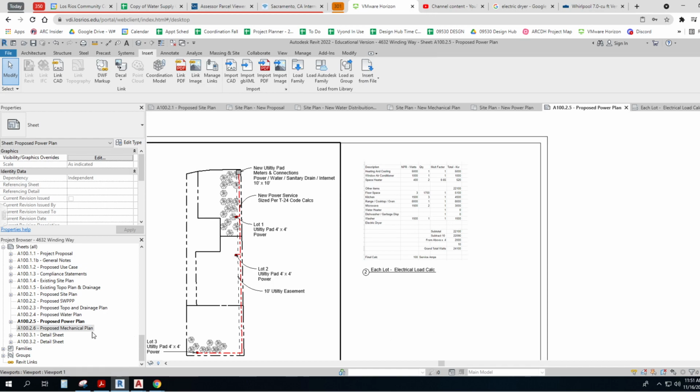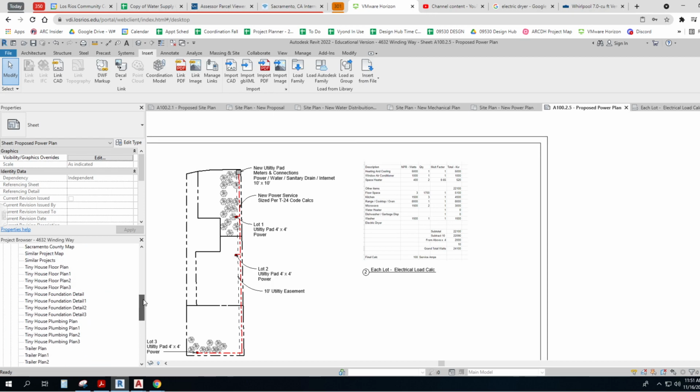I noticed that when I added to it, the property lines also showed up on the existing as well. They do. You have to hide them. It's a right click hide. So I can right click hide it on the existing, but it will still show up on the proposed. Yes. Awesome. Because I saw that on there and I was like, wait a second, I want them on the proposed, but not the existing.